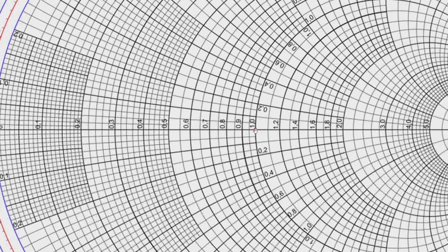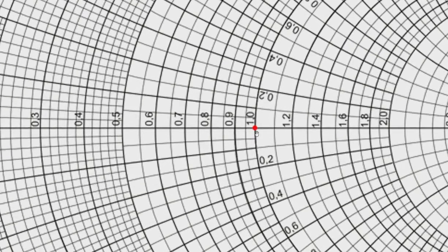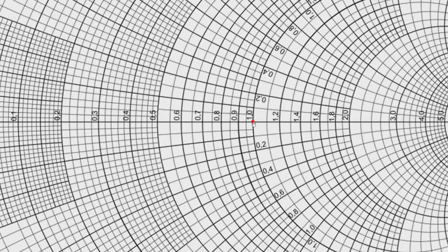Now, you could use the Smith chart with transmission lines with different characteristic impedance. Like you could use it with 50 ohm line, you could use it with 75, 450 ohms, whatever you want. And you normalize it so that whatever your characteristic impedance is going to end up right here on 1.0. Let's think about it this way. Say we measure the impedance of our line.